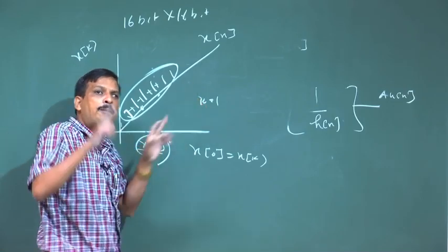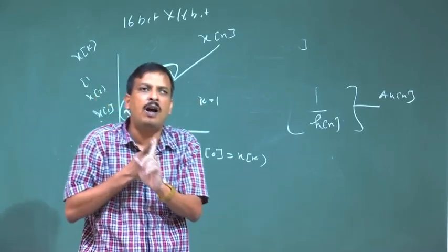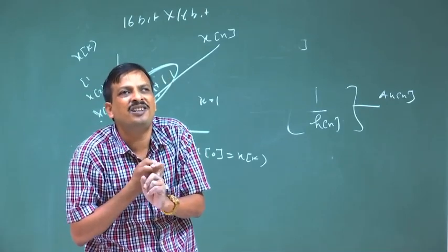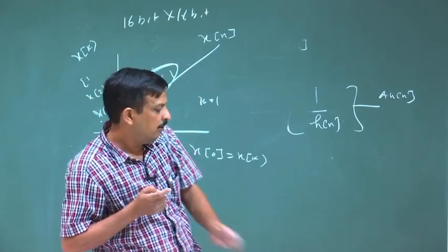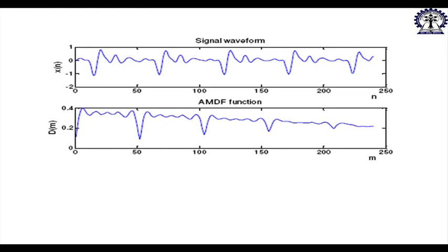Okay. So, the deviation will be minimum when it matches with the period. So, if I plot the deviation, the plot will look like this. Minimum deviation will happen at the period, or at the f0. So, this is f0, this is twice f0, this is thrice f0. Okay. So, this technique is used to find out the fundamental frequency when the computation power is less.